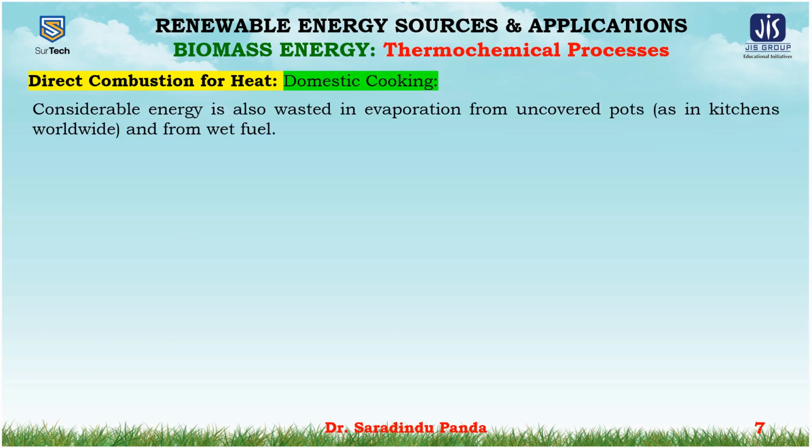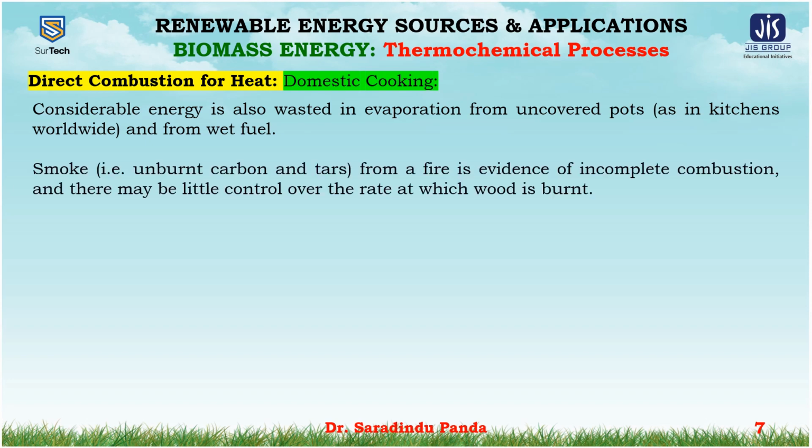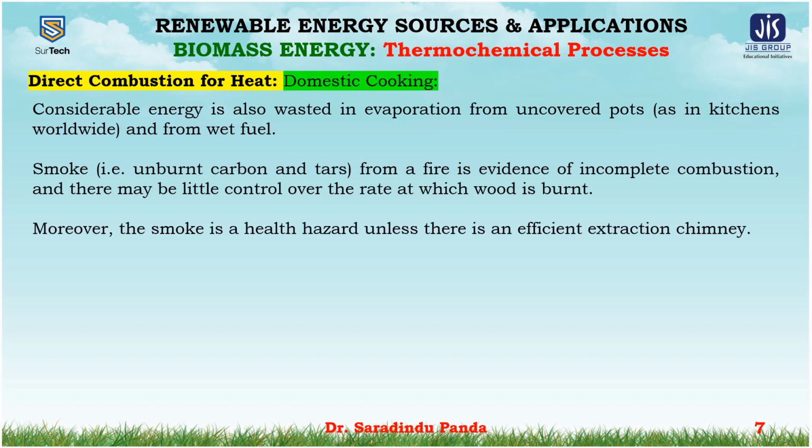Considerably, energy is also wasted in evaporation from uncovered pots and from the wet fuel. Smoke from a fire is evidence of incomplete combustion, and there may be little control over the rate at which the wood is burned. Moreover, the smoke is a health hazard unless there is an efficient extraction chimney.